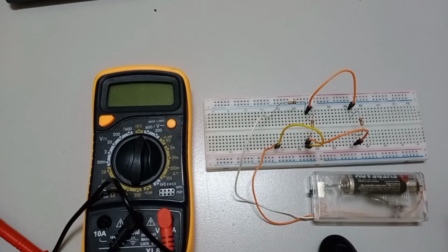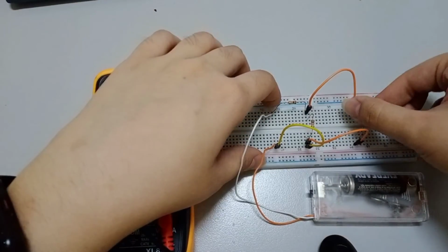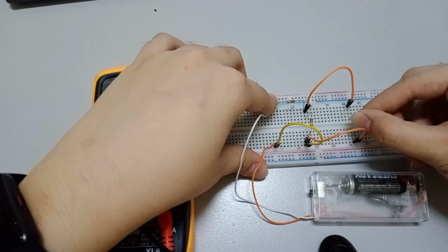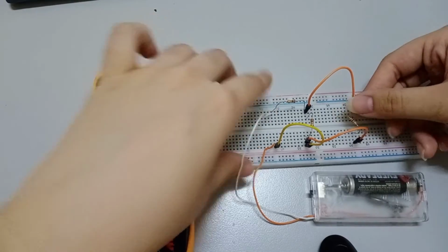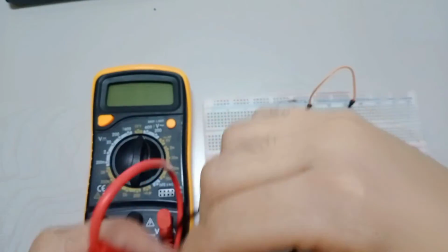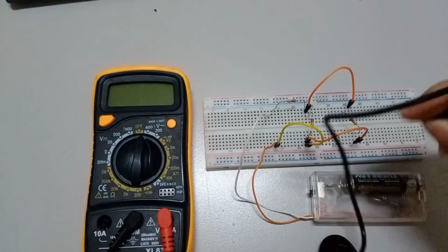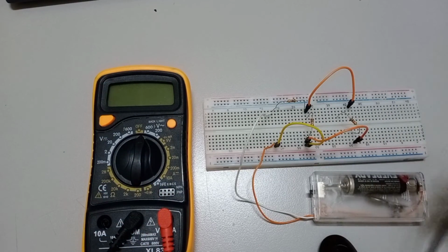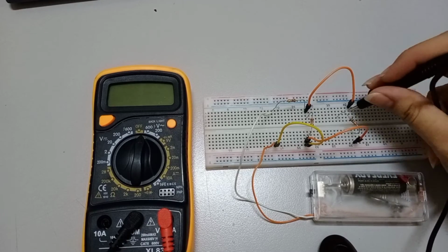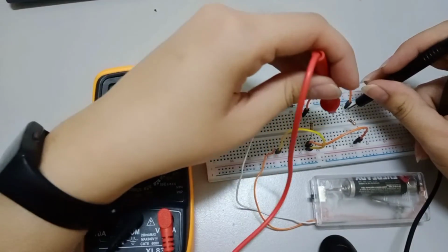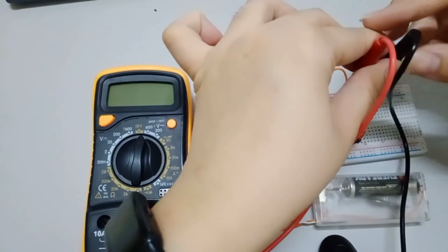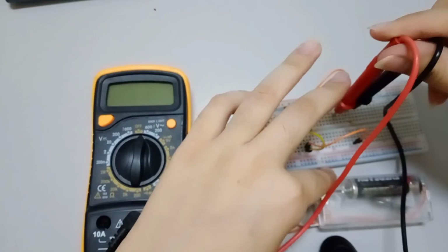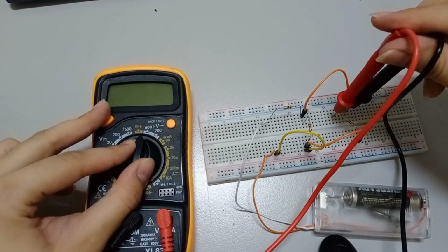To determine the partial current at test point GH, we need to break down the resistor tree and connect it somewhere here. Then use the probe and connect on the jumper wire here and the one on the resistor tree here. After that, switch on the power supply and the multimeter.